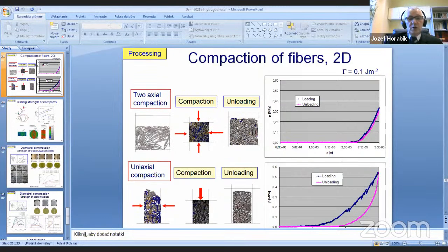And coming to conclusions, I'd like to say that DEM has proved to be effective in studying numerous technological processes in biosystems engineering. It allows insight into mechanism of stress transmission in granular solids that enables investigation of effect of properties of individual particles on behavior of bed of particles, and particularly the bonded particle model reproduces many features of behavior of solids like elasticity with ultimate yield, hardening, softening, and fracturing.